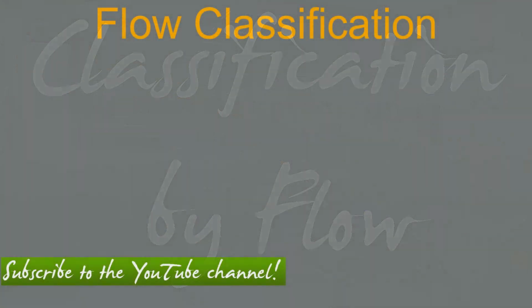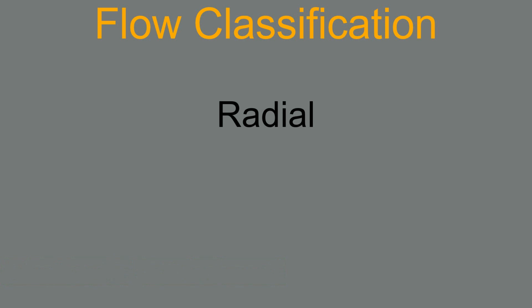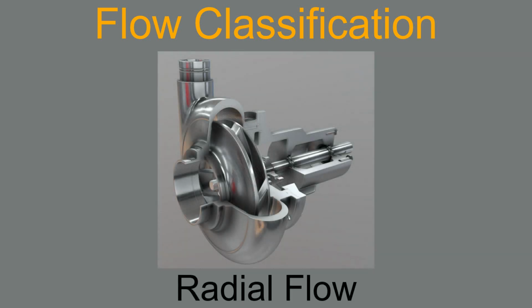In addition to classifying the pump by impeller type, we can also classify the pump based upon the flow. Centrifugal pumps are categorized based upon three flow types. These are radial, axial, and mixed. Radial flow centrifugal pumps are the most common of the three used in industrial applications. Radial flow pumps discharge fluids perpendicular to the main pump shaft. That is to say, they discharge the fluid at a 90-degree angle compared to the orientation of the pump shaft. Radial flow pumps are ideal for many pressure and flow applications.